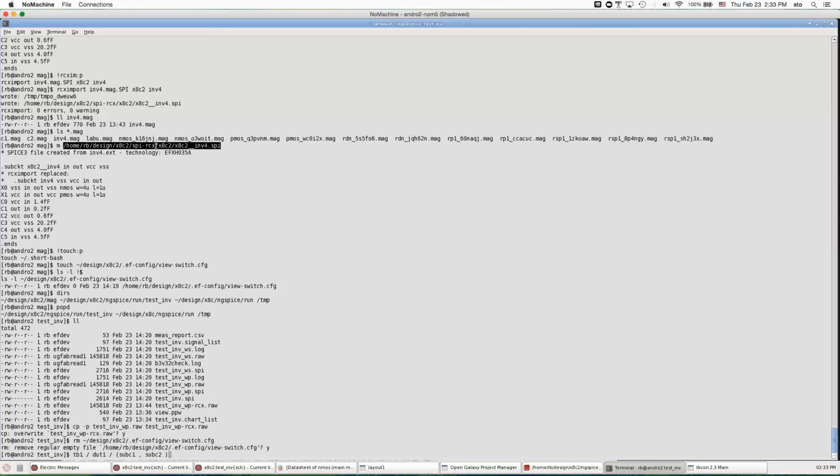They essentially redefine subcircuits if there's a subcircuit match between those RCX names and the native electric subcircuits. The RCX will redefine the electric-created subcircuit and, quote unquote, take its place. That's not to say that all the hierarchy issues have been worked out or tested well, so that's also a work in progress.